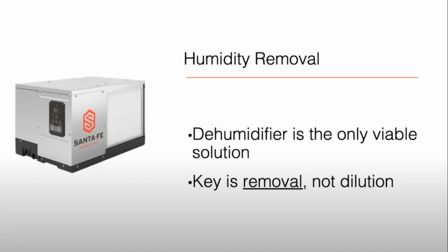Looking at humidity removal, the dehumidifier is the only viable solution. The key word here is removal, not dilution. All the other forms of conditioning a crawl space we talked about are dilution. The focus in the building industry has been building a high efficiency and tight home. The reason why we have been talking about code is because it's helping achieve those goals.